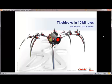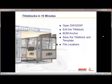I'm Jim Byrne from Desai Solutions, and this is Titleblocks in 10 minutes. During this presentation, we'll take advantage of existing title blocks created from other CAD systems, modifying those title blocks, setting up anchor points for BOMs and revision tables, saving that title block and template off, and we'll also talk about file locations so that all users in your organization are using the same title blocks and templates.